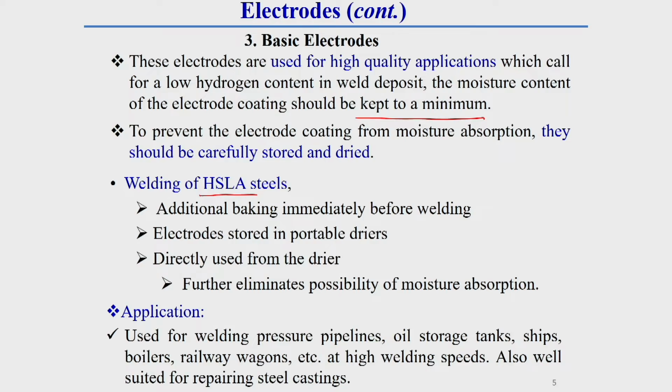Once you keep the electrode over there, whatever moisture and other things are present will be heated up and removed. That is why, when we use HSLA, this drying operation is done immediately before welding. The moisture absorption will be removed and the weld quality will be very good.